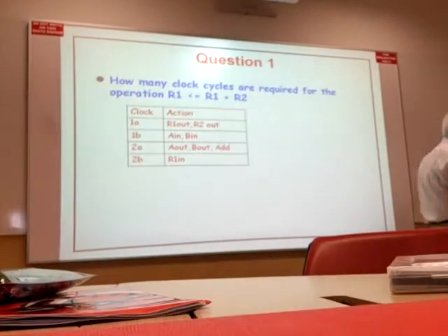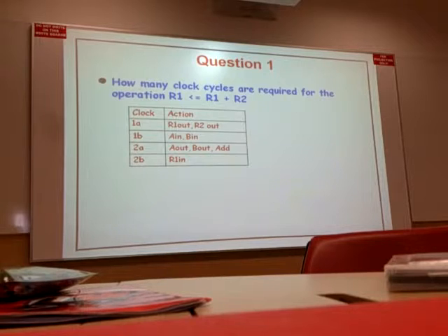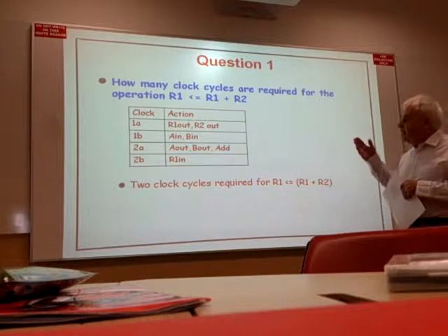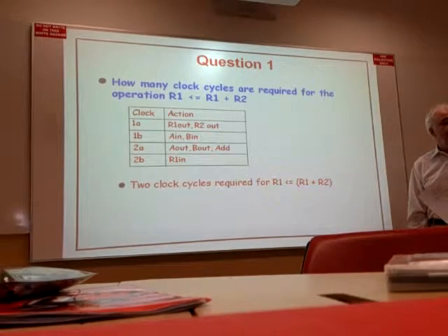Okay, so introducing those registers, if we have 3 buses, we don't really need those registers. In fact, introducing those registers doesn't really achieve much because it actually requires more clock cycles to do the calculation. If you didn't have the 3 buses, then you usually need these registers for the ALU. But if you have 3 buses, you don't really need them.